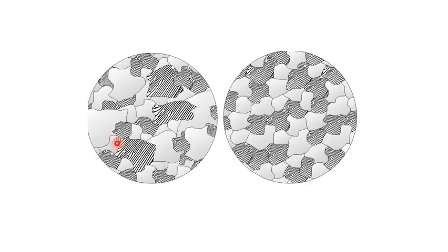As mentioned in the last slide, the energy of the grain boundary is higher than the energy of the grains, because the atoms in the grain boundary are not as well bonded as the atoms inside the grains. Having said that, it means that the chemical activity of the grain boundary area is higher than the chemical activity of the grains,